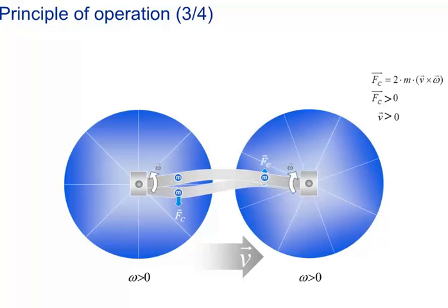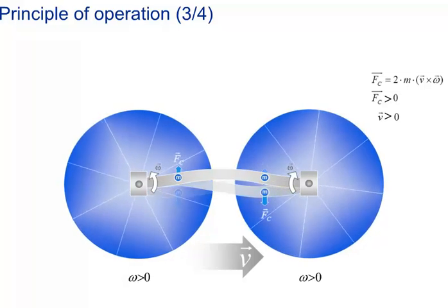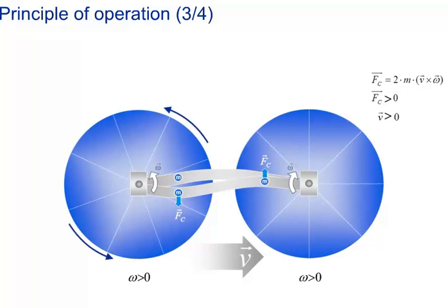In case of no flow, the fluid, or balls in our example, would not experience any Coriolis force. In the case of a moving fluid, the Coriolis force affects the fluid and consequently the tube, bending it down or up. The direction of the Coriolis force depends on the direction of rotation present at a particular moment of time. In the left half, the instantaneous rotation is anticlockwise. In the right half of the tube, the instantaneous rotation is clockwise. Consequently, the tube is bent downwards on the left and upwards on the right. The relative distortions of the 2 points are not in phase with the flowing medium.